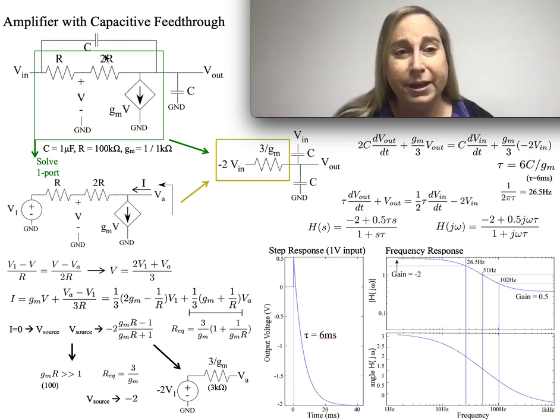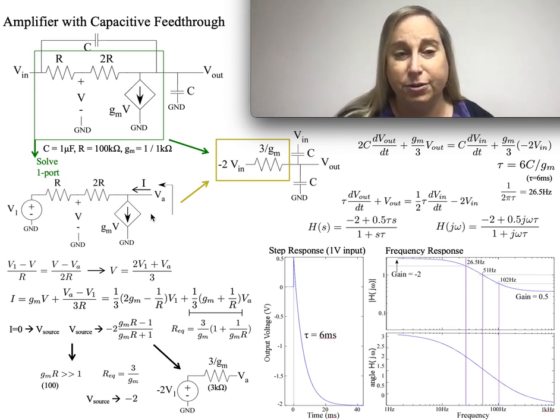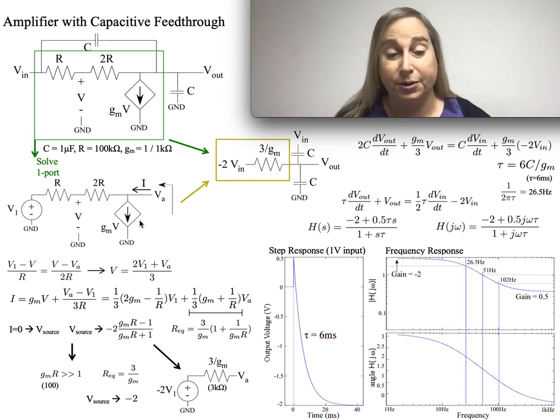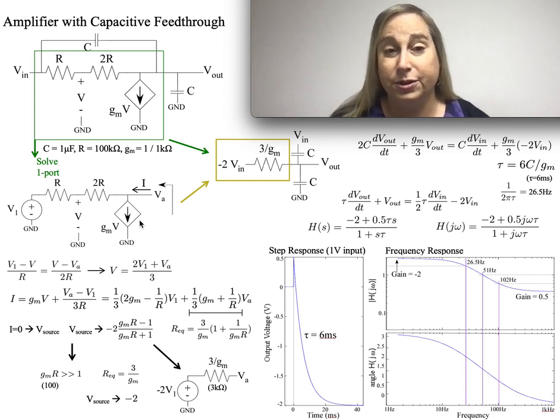Now, to make this easier to start with, realize that what's in the green box can basically be combined into a simple one-port structure. If you include the input voltage into it, you can reduce that down to simplify it, and the circuit you would get would look something like the structure you see down here. Again, the voltage, 2 resistors, looking at a voltage source here that then sets that current source. A very simple model of what an amplifier would look like, and again, a very straightforward linear circuit which you can solve.